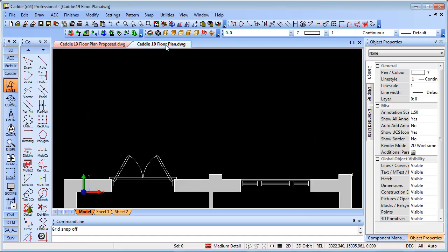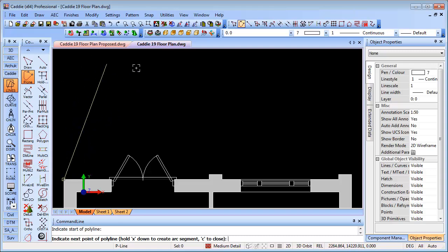So going to a base plan here. If we were to draw out firstly a polyline, for instance, here you'll notice I'm set to endpoint snap, and moving the cursor around, we're actually in free move mode, and here there's no endpoint to snap to. So clicking down, nothing will actually find its way.